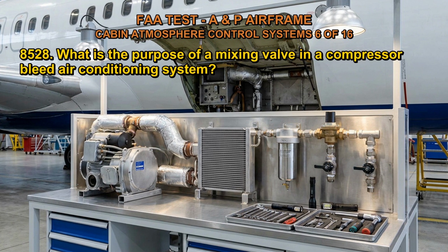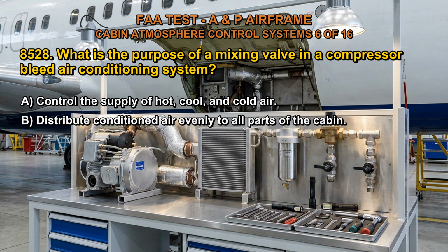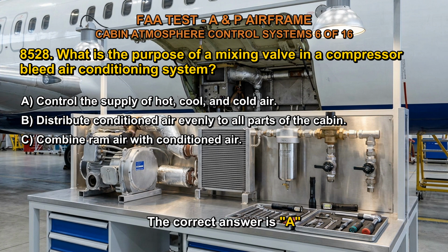8528. What is the purpose of a mixing valve in a compressor bleed air conditioning system? A. Control the supply of hot, cool, and cold air. B. Distribute conditioned air evenly to all parts of the cabin. C. Combine ram air with conditioned air. The correct answer is A.